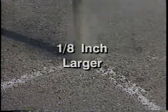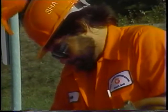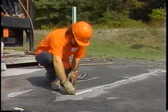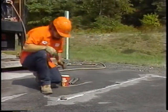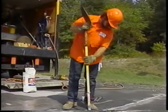Next, drill holes with a diameter that is 1/8 inch larger than the diameter of the sensing probes or the PVC pipe if lining the holes. It is imperative that the microloop or magnetometer probe should be mounted in a stable, vertical position. Lining the hole with PVC pipe ensures that the probe will remain vertical if the hole walls collapse. The required depth of the hole should be defined on the construction plans.